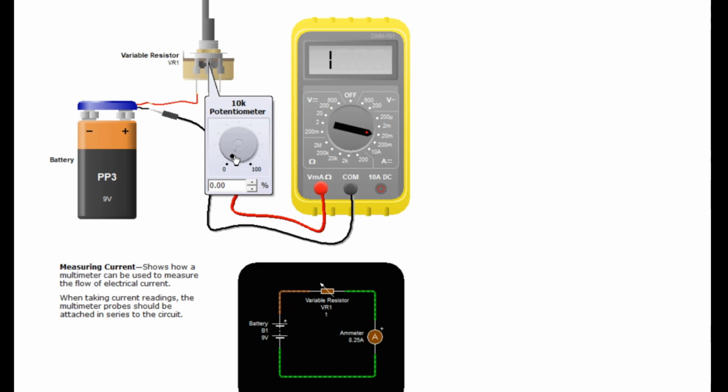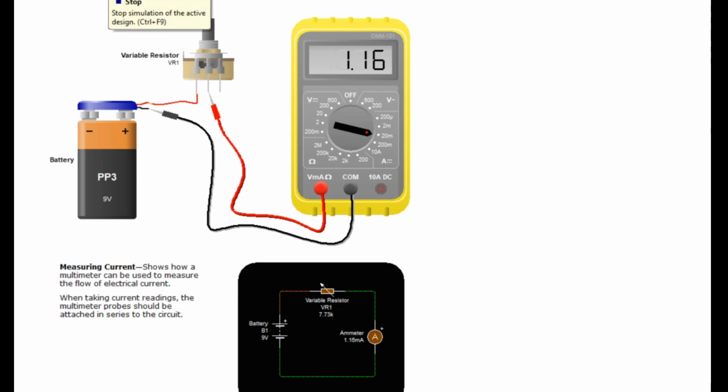Impedance of the multimeter for current measurement. Ideally, the impedance should be 0. When you connect a multimeter in series to measure current, it introduces some impedance, resistance, into the circuit. This is known as the burden voltage or burden resistance. The magnitude of this impedance varies among multimeters and depends on the selected current range. The impedance of the multimeter affects the circuit it's measuring.